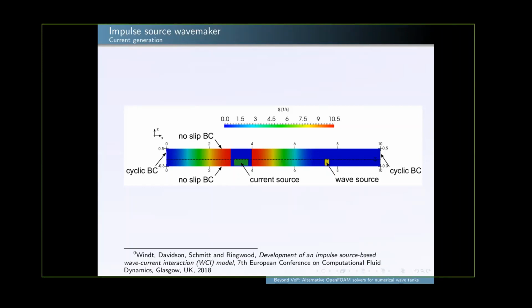That way, if the wave was there as well and we had these wave horizontal components, it would mess up our calibration of the current. So where the current source is, there are no waves. It's in between the two beaches. Then we push horizontal velocity out, it goes through the beaches, and it doesn't see the beaches because they only absorb vertically. Then on the other side of that, we have our wave source. That's how we've been implementing waves and currents.